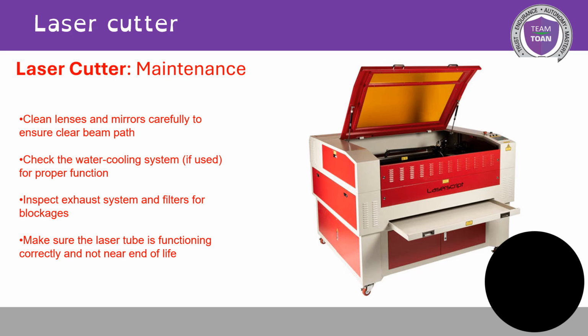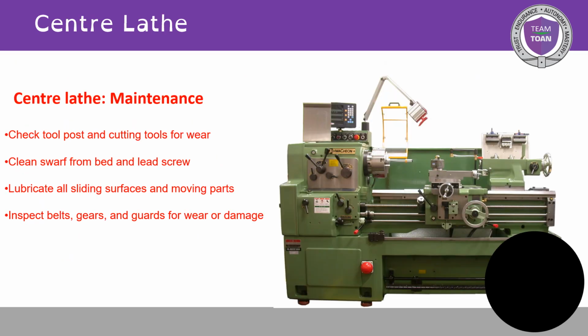You need to check the water cooling system if you have a water cooling system in a laser cutter. We do not at school, but more industrial stuff, industrial laser cutters do. Inspect the exhaust system and filters for blockages and make sure the laser tube is functioning correctly and not near end of life.